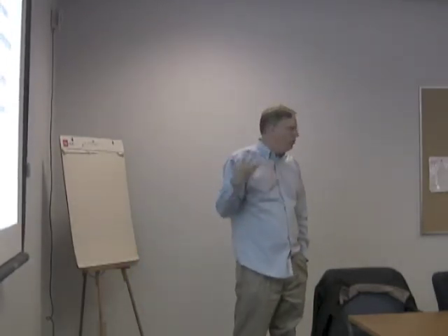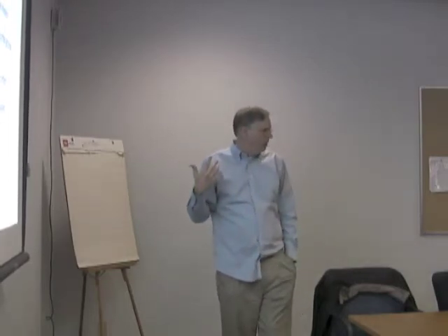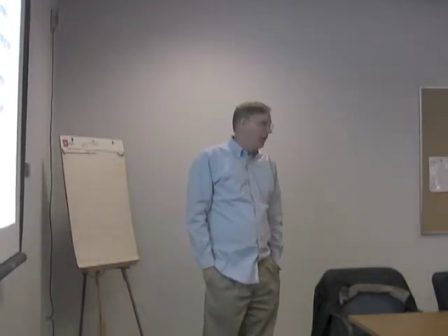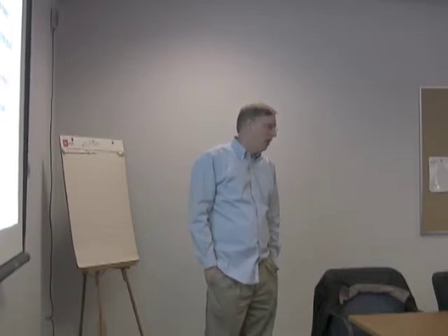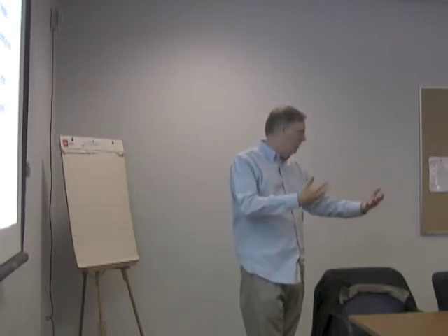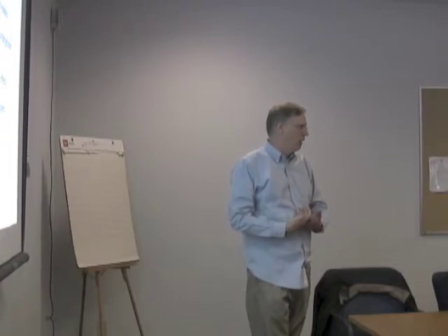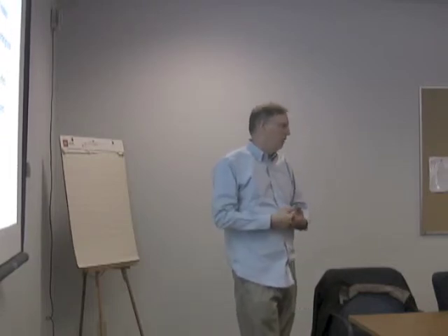SCEC is in particular using microtremor data to build 3D crustal models as a first cut at the velocity structure, but also then using the available data to build a 3D model. The 3D simulations now are fast enough to allow rapid feedback, and this is really a key. They can turn these around in about a month so that you can see the results, compare them to your data and observation, change the model and have feedback and rerun it. If this took 2 years to run, you can't get that. So that's really a huge step forward just in the calculation speed that's available.